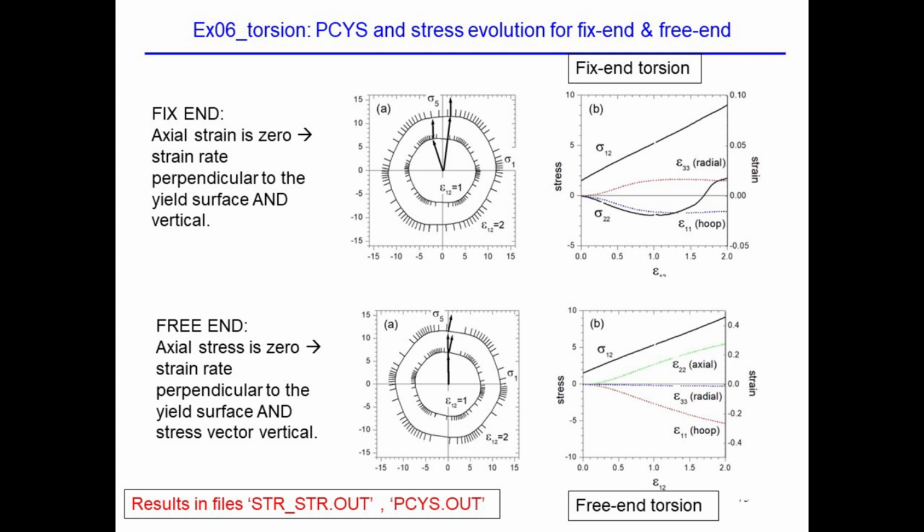So this point is such that the strain rate is perpendicular here, because this vector that is perpendicular has an epsilon dot 22, which is this component, equal to 0. You are forcing epsilon dot 22 to be equal to 0, so it has to be perpendicular. So if you have the yield surface, you look where the strain rate is perpendicular to it. That is the point where you are going to be activating the stress state, sigma here.